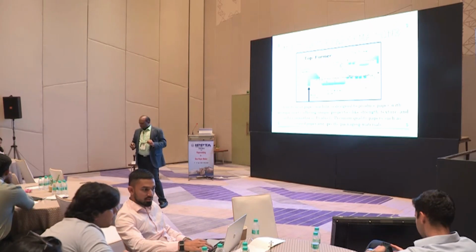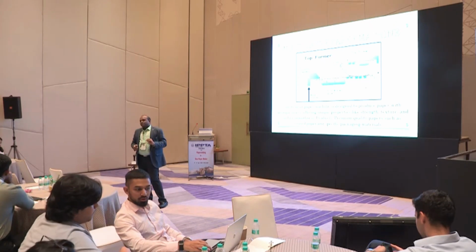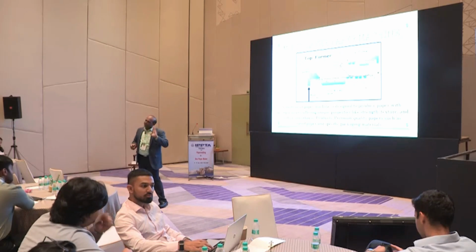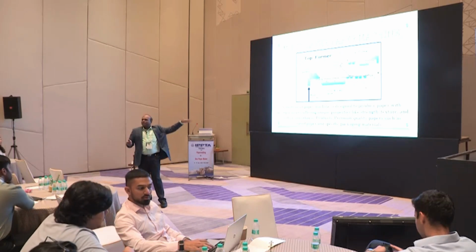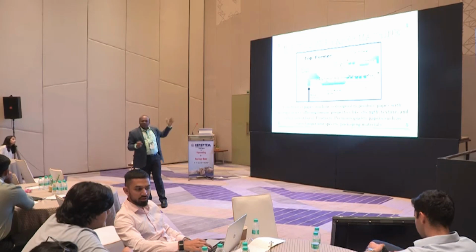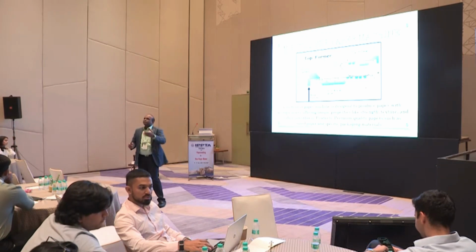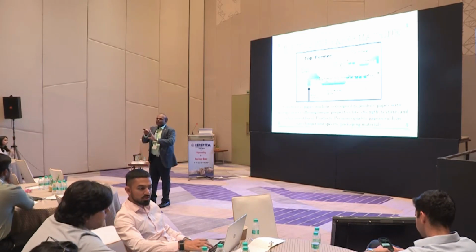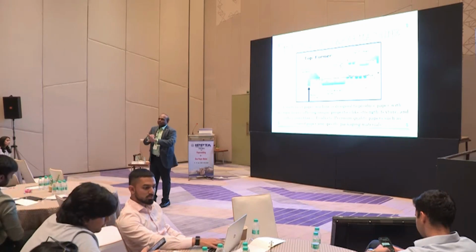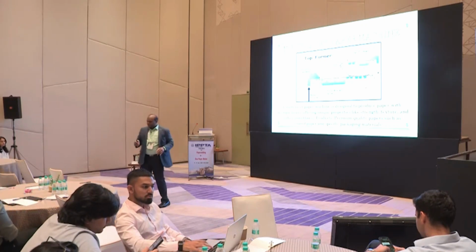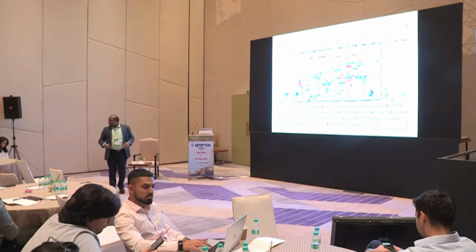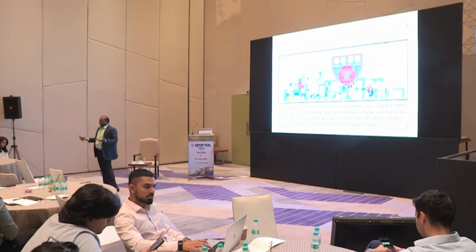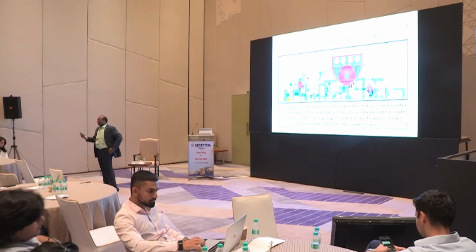And here also we can use different types of pulp in different layers. Yes, possible. In the top layer we can use a different furnish, and in the bottom layer you can use a different furnish. A sweet box, for example, inside it will be grey back, and outside it will be colorful white. Right? Yeah, it can be. This is just the former section. After that we can do coating on both sides or a single side, whatever we want.